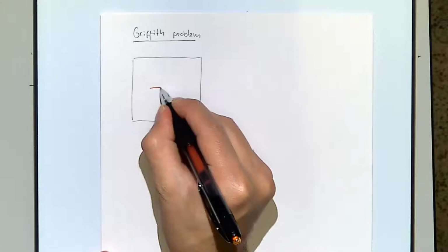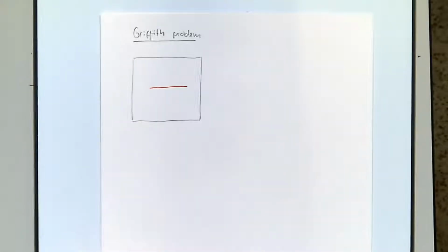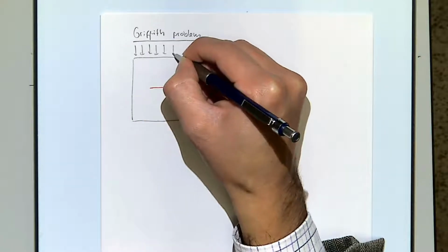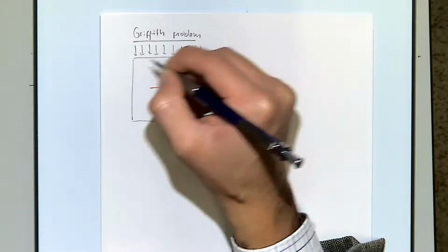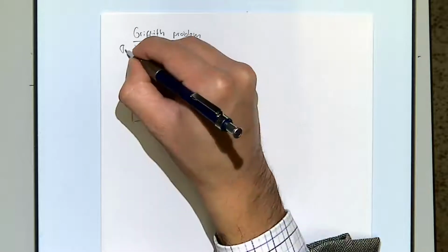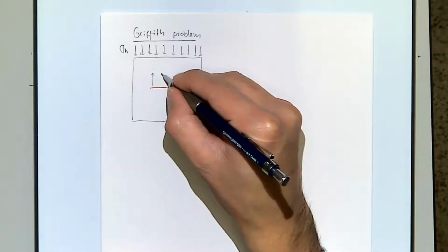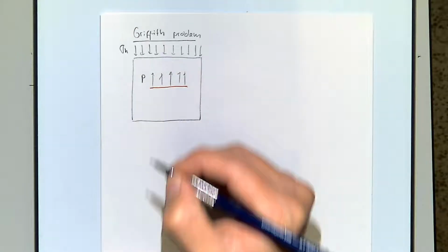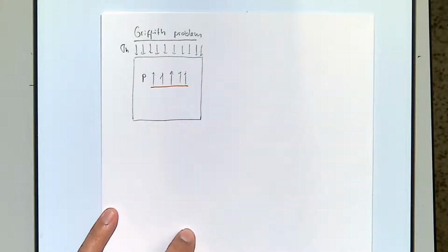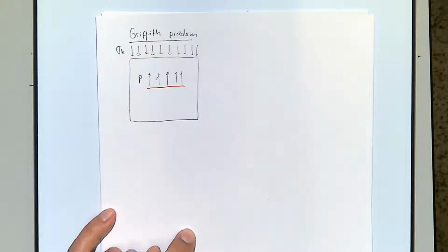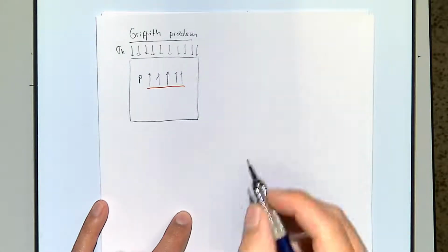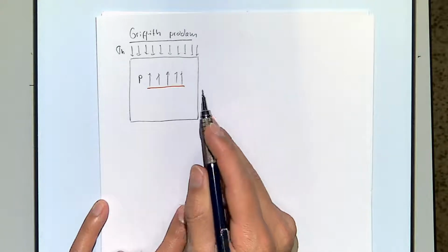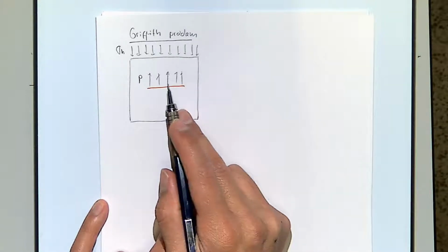So I have a fracture which is pressurized, and this is subjected to far field stresses sigma h, pressure inside the fracture P. The first thing that Griffith does is to simplify this problem. These will be the properties that we have in the subsurface, right? We have a far field stress and we have a pressure inside the fracture.